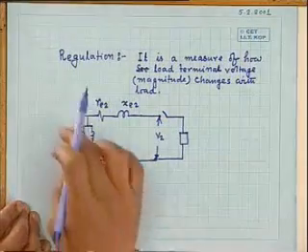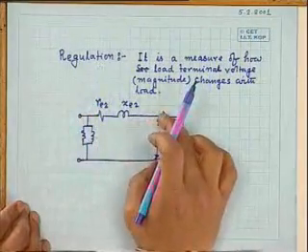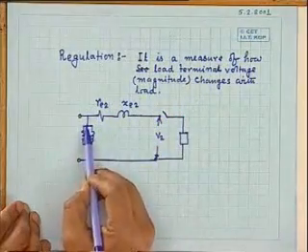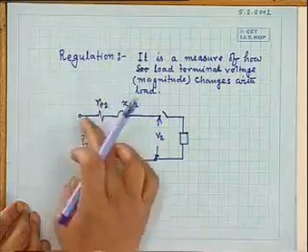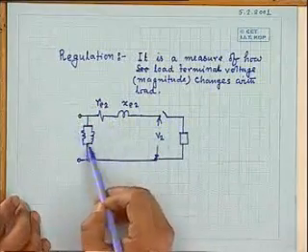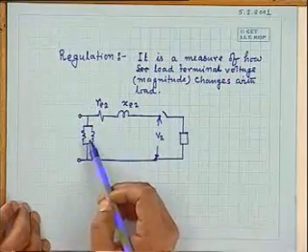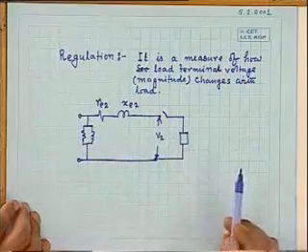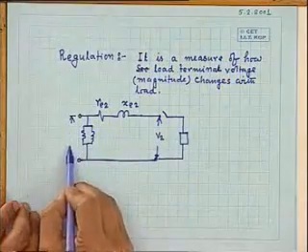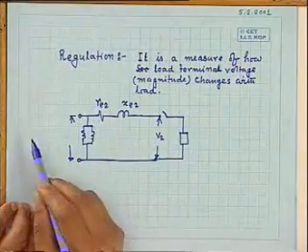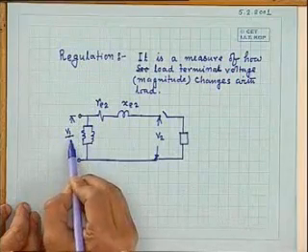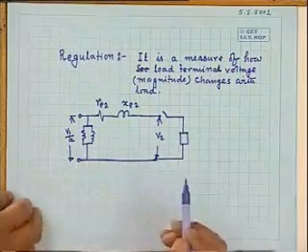As you can see, the difference of the voltage between this point and this point is in no way related to what current is drawn by this magnetizing branch. The difference of this voltage and this voltage will be decided by the drop here. So this parallel branch impedance does not come into the calculation so far as regulation calculation is concerned. And this voltage, what should I write? If V1 is the input voltage, V1 by A.